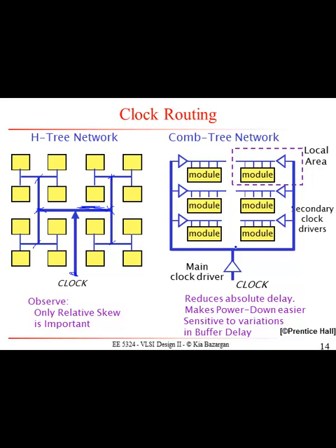Essentially what you have is like the football goalpost, and right off the bat, you would know that the clock signal is going to arrive here earlier than here. And also you would know that this signal here is going to get its clock value earlier than these guys. But if all of this is within an acceptable range of clock skew, then you're probably fine.